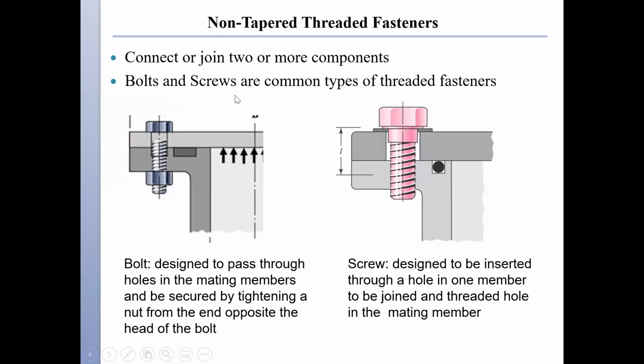But as you're going to see, when we start learning about these bolted connections, the grip length for each of these connections is going to be different. Everything under the head of the bolt here, all the way through the nut, is within the grip. But when I look at a connection like this, the grip length does not extend all the way through the end of my screw.